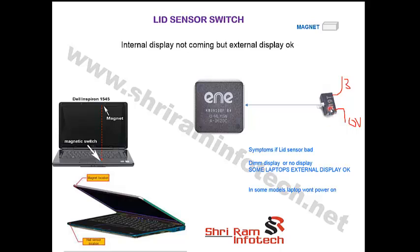In some laptops, if the sensor is short, then your internal display will not be there and the external display will be there. At that time also you have to concentrate on this sensor. In some laptops there will be a dim display, where the display is there but the backlight is not on. At that time also you have to concentrate on this sensor. So this is the lid sensor, so you have to focus on the lid sensor. You have to find the lid sensor whenever such types of problems occur.